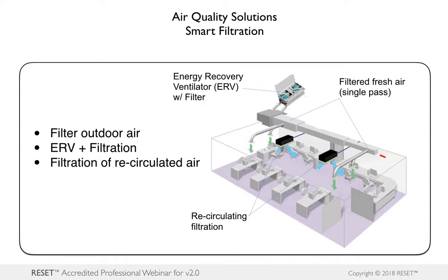Now, there is an increasing focus, and again, with some of the different field studies and research and case studies that we've been particularly interested in, there's an increasing focus on recirculation units. So these are units with filtration, and there's a decentralization of air treatment as a solution. So less focus on a central air handling unit and a central BMS system, building management system, and instead an increased focus in how to develop local BMSs to provide more accurate control on a space-by-space level.